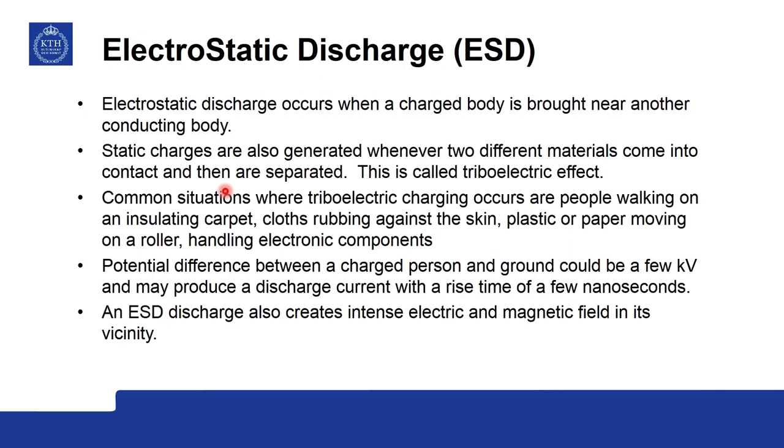So, they have to control electrostatic discharge at any cost. While handling electronics, you use straps on the wrist, then grounded, to reduce the danger of your body getting charged and damaging the components.